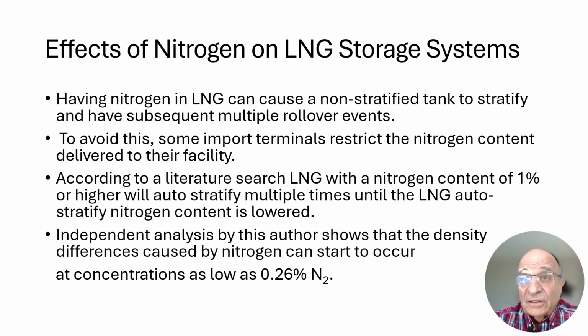My own studies and analysis show that as little as 0.26% nitrogen in LNG will cause a reversal of the density change that occurs as your LNG weathers. So I'll go as low as saying 0.26% is a concern, but in general, the literature says at 1%, you will get auto-stratification.